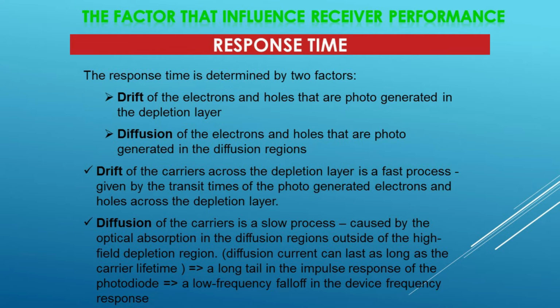Diffusion current can last as long as the carrier lifetime, which means a long tail in the impulse response of the photodiode, which means a low-frequency fall-off in the device frequency response.